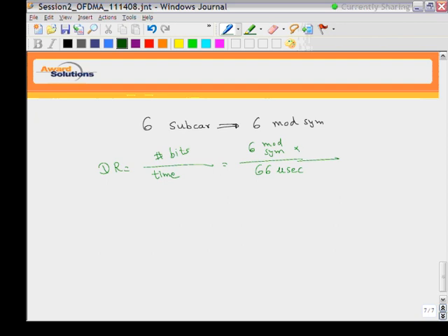Now what modulation symbol? So we have various techniques. What is the highest order modulation scheme in LTE? And how many bits does it represent? Okay, 64 QAM and 6 bits. Perfect. So let's say these are 64 QAM modulation, and each 64 QAM modulation symbol represents 6 bits. So 6 bits per modulation symbol. Okay, so we got 36 bits being represented in 66 microseconds.